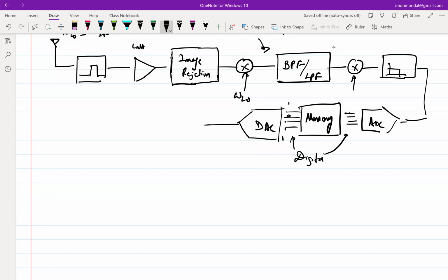When you have an analog signal and you sample it, you are going to have aliasing, right? Or, I shouldn't say aliasing. When you take an analog waveform and sample it, you are going to have tones, right? Similarly, when you take digital bits and you associate an analog value with that, it is equivalent to sampling an analog signal at this node, which means you are going to have tones. But the information that you are going to send out should not have tones,